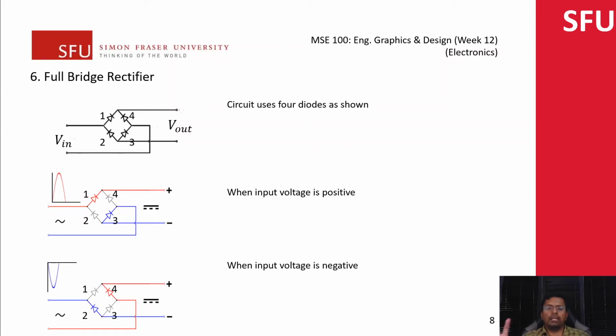The next component we'll be looking at is known as a full bridge rectifier. The idea here is you take the diodes that we just looked at, and put 4 of those in this square pattern over here. This input is going to be a sinusoidal input. You wouldn't typically connect it directly to the power source, you'd have a transformer to reduce the voltage, but just imagine a sinusoidal wave coming in here, and then you have this output over here.